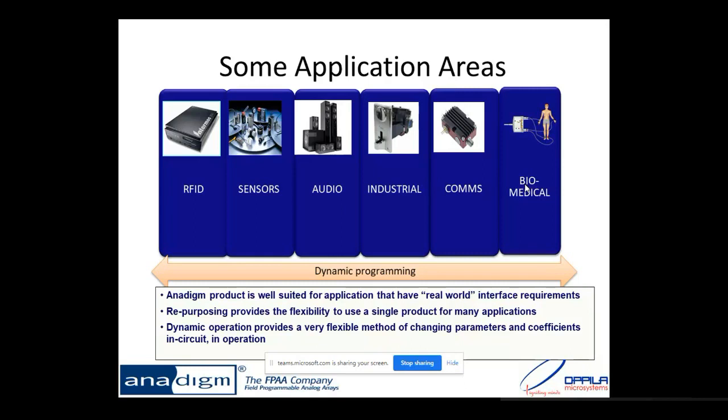One more thing is that those biomedical signals are also analog in nature. So if we convert that analog into digital, some approximation will be there. You can't get the same signal you are getting from the human body. So 100% it won't be the same signal. But in this FPAA, whatever we are extracting from the human body, we are feeding it as it is. We are not changing it at all. Those biomedical signals can be fed to the FPAA.